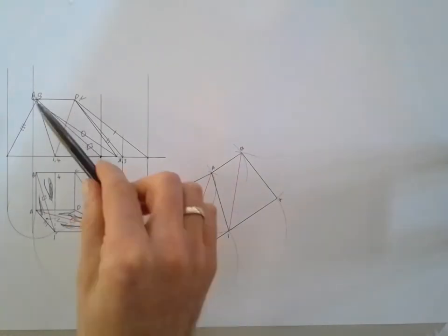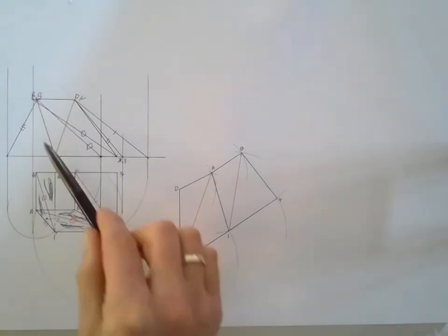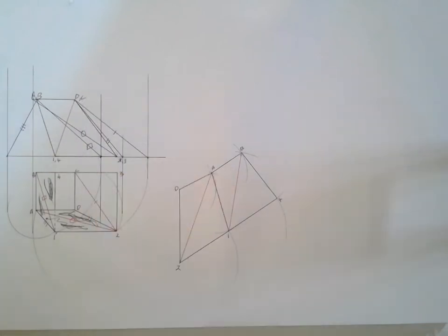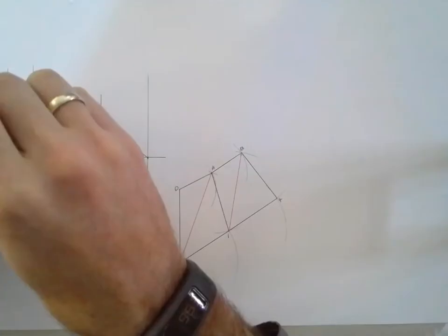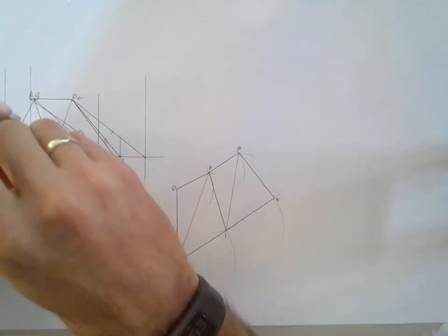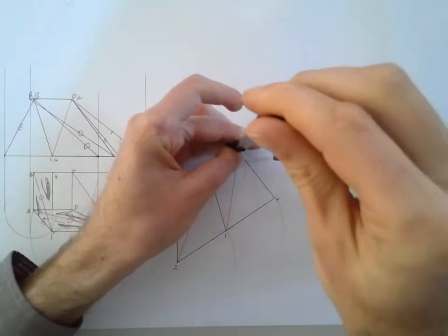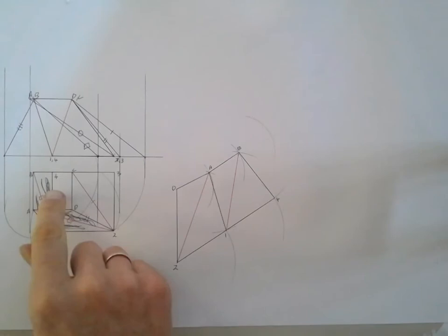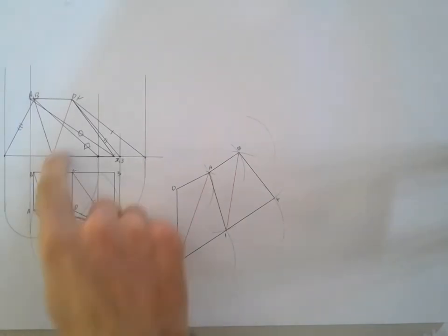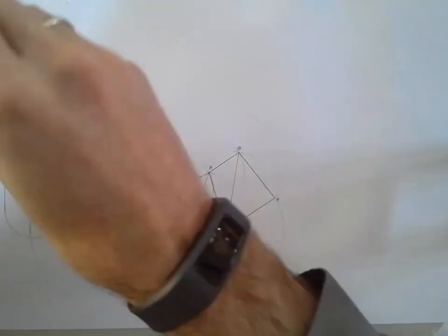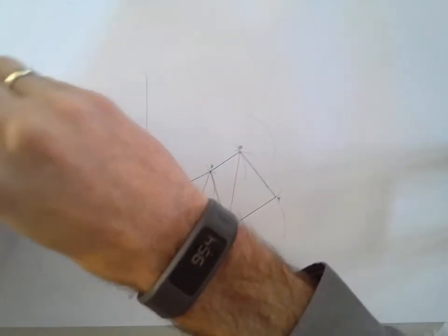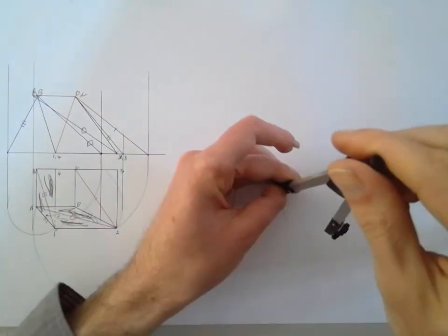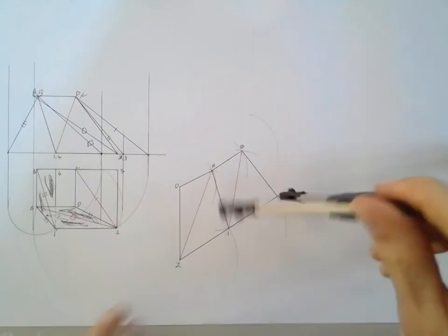Okay, you can see you've got the one triangle B, from B to 4 to point C at the top here, B to 4 to C. So for that triangle, you need the true length of BC, which is already in the top view. Take that length, place it on point B, arc it out, and then you need the true length of 4 to C, and that's here in this triangle that you can see in your front view. So that's already a true length. Open it up to point C, and then place that on point 4 and make another arc.